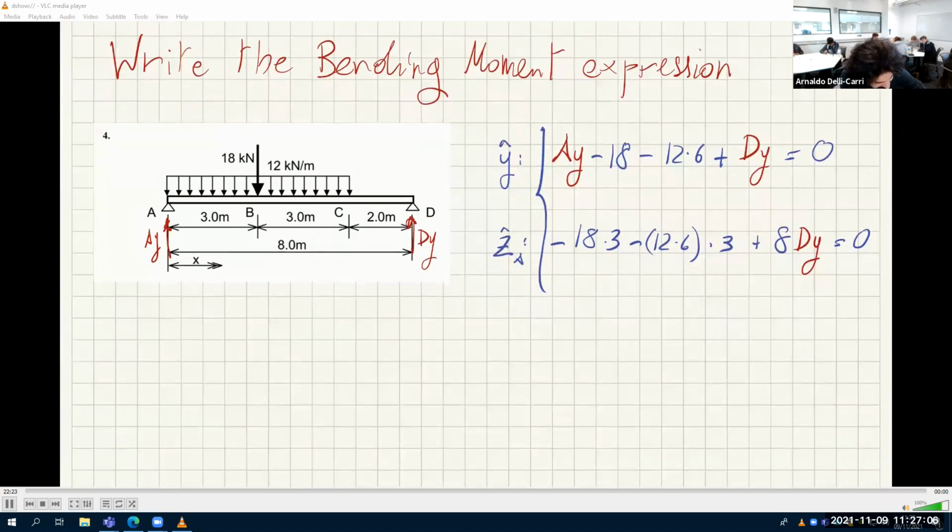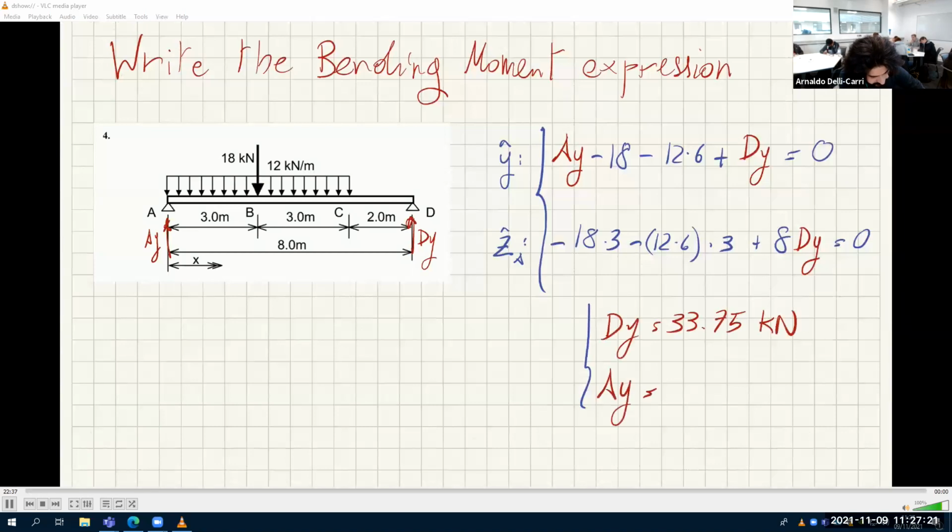Sorry, can you say it louder, please? 33.75 for DY. So DY is 33.75 kilonewtons. And how much is AY? 56.25 kilonewtons. There you go. Thank you very much. So these are the reaction forces.